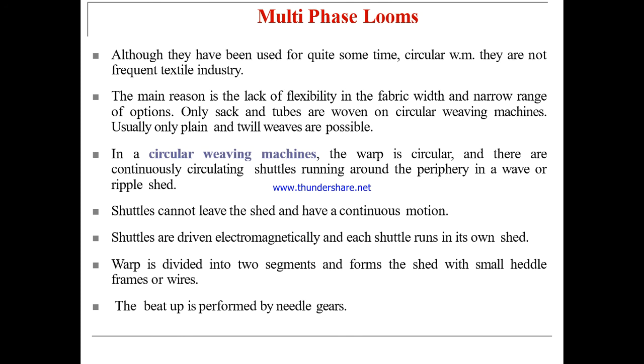Continuously the shuttle will insert the weft. Shuttles are driven electromagnetically and each shuttle runs in its own shed. The warp is divided into two segments and forms the shed with small heald frames and wires. The beat-up is performed by the needle gears.